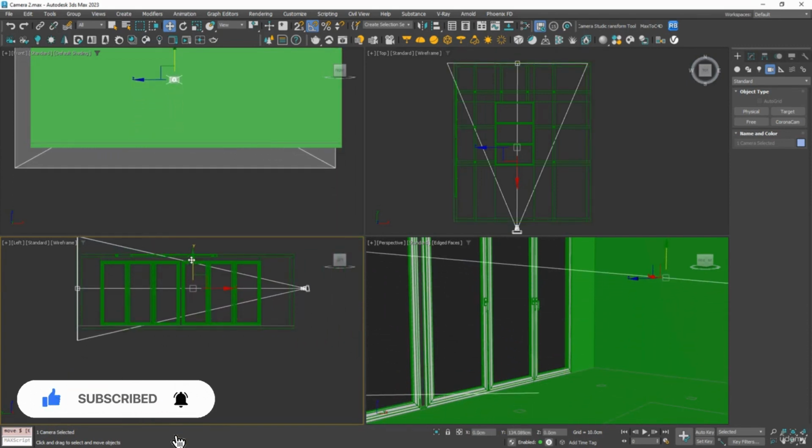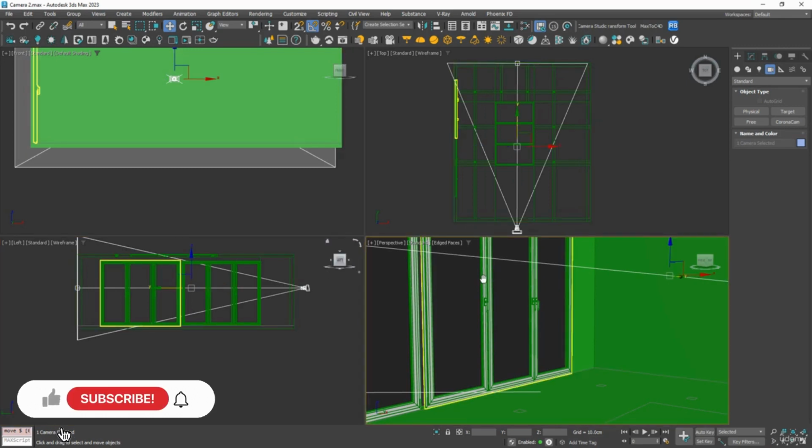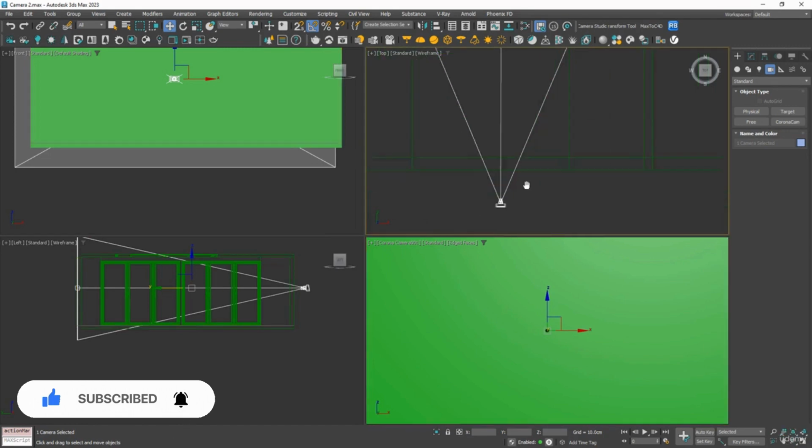And I like to keep my cameras somewhere between chest and head height, as I just feel that's a more natural view, something like the photographer is going to do, and I think we're just more used to seeing images like that. So we go back to perspective view and press C on the keyboard. Notice that we're actually just looking at a wall, and that's because our camera's behind this wall.